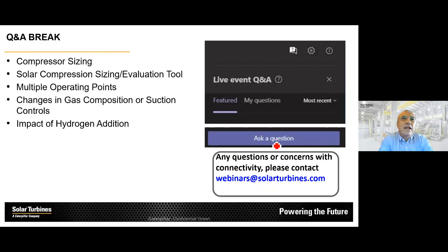If you look at the operational map, you will see that once you approach surge, your head versus flow characteristic will flatten out. The reason why I'm a bit vague is because the signs of approaching surge are different from compressor to compressor. Oh, that makes sense, Rainer. Those are all good characterizations of when you're approaching that surge point. So thank you for clarifying for the audience.